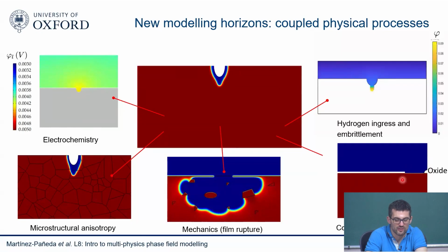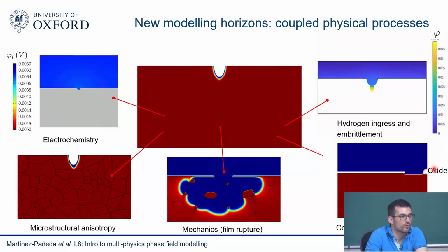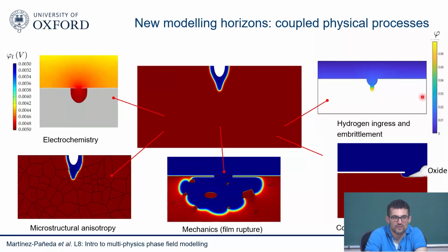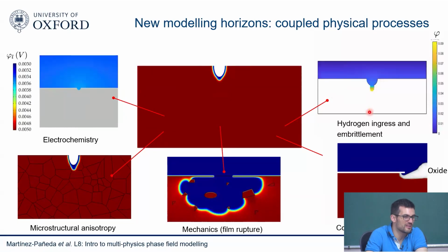So you may have a phase field for the evolution of the corrosion front and one for the formation of other products. So that's something that you can also resolve. You may also have hydrogen. All the problems that I mentioned with hydrogen come in through corrosive reactions. So everything that we discussed in the seminar about hydrogen will happen here as well. Hydrogen uptake will happen in this corrosive environment.